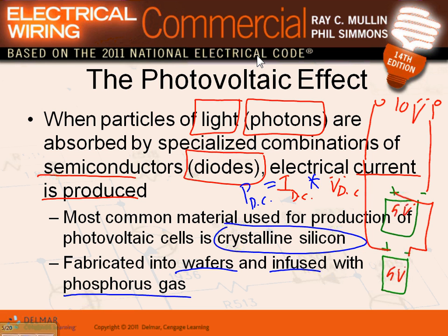10 volt. Remember how Mr. Ryman told you, put two panels, each one of them 5 volt by design, you put them in series, what happened to the total voltage? You get 10 volts. Now suppose each one of these panels is carrying 1 amp. I'm just throwing in 1 amp. If you put them in series, does the amp change when you put sources of power in series? Stays the same.